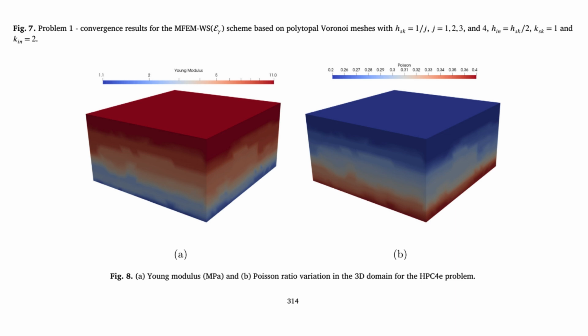Ah, locking. Yeah, I've heard of that. That's when you're trying to model materials that are almost incompressible, isn't it? Like rubber or materials where the Poisson ratio gets close to 0.5. Exactly. Standard methods, particularly these stress-mixed methods, they just sort of seize up. They lose accuracy dramatically when you get near that limit. It's a real barrier. And wasn't there another difficulty tied into that? Something about making the stress tensor symmetric.